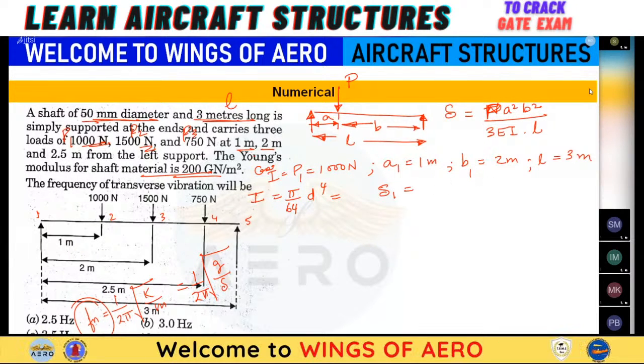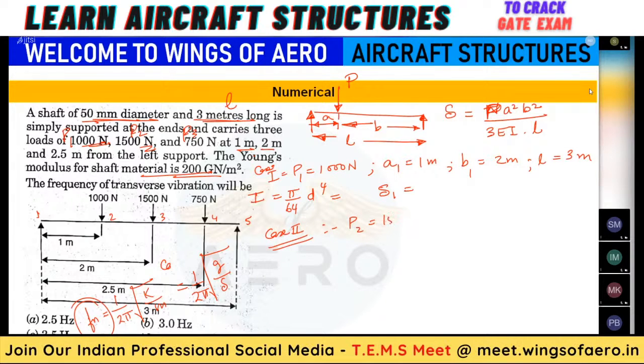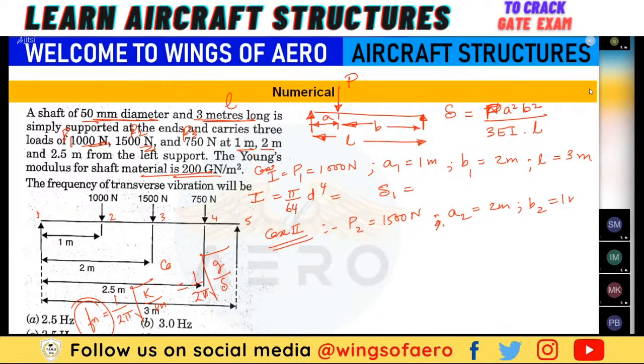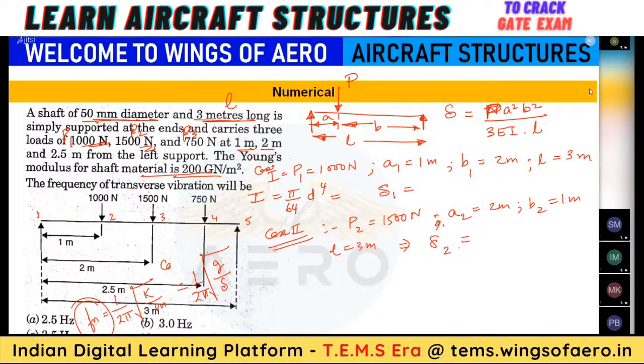Second case, your load P2 is 1500 Newton. On that time, what will be the A2? A2 will be 2 meter and B2 will be 1 meter. L is the same, 3 meter. Substitute the values in the general formula, you will get the value of del 2.